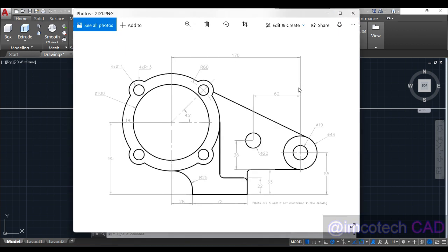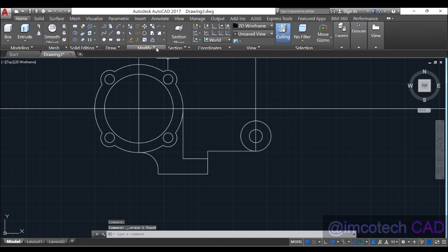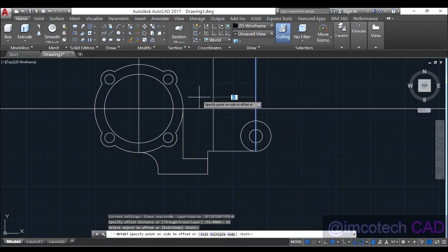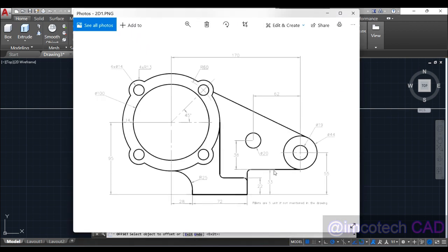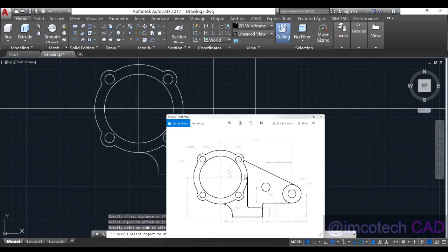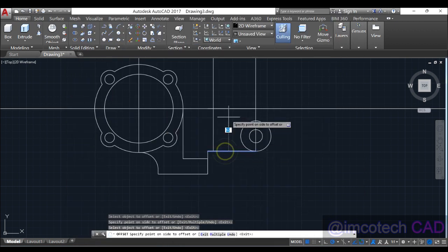Okay, we definitely still need this line because we are going to offset this in by 62 units right now for this little circle. So offset by 62 units from this place in. Right now we are going to check again. You can see that this baseline here, not this line, not this, but this particular line will offset it upward by 38 units to make a cross on this vertical line. Okay, so offset by 38.